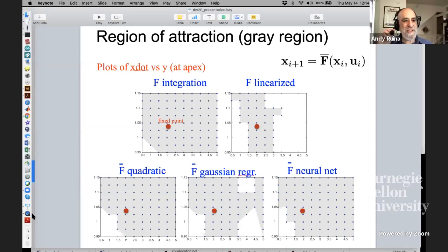You do an optimization on this quadratic cost, and then you evaluate the quality of your control by the basin of attraction. Why not just more directly optimize on the basin of attraction, or perhaps even instead of optimizing for quadratic cost, do something even cheaper, like optimize for how close you can get to your fixed point in one step, and skip the quadratic cost altogether.